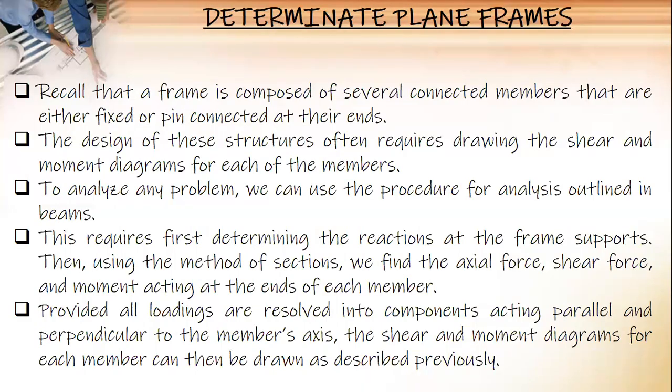So, to analyze any problem, we can use the procedure for analysis outlined in beam. So, as if you are analyzing a beam. This requires first determining the reactions at the frame supports, and then using the method of sections, we find the axial force, the shear force, and the moment acting at the ends of each member.